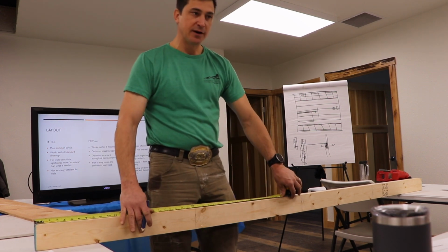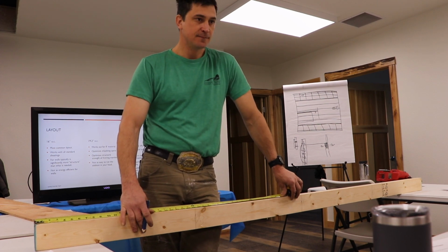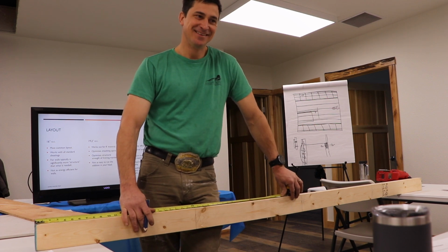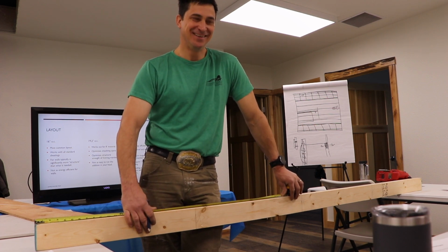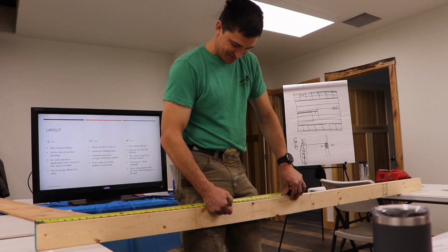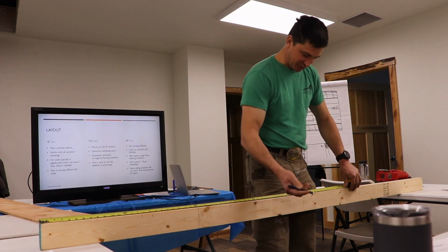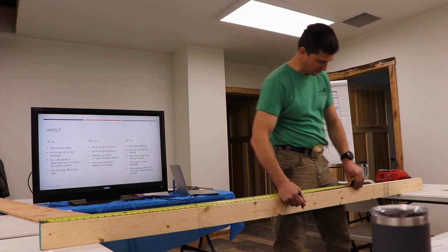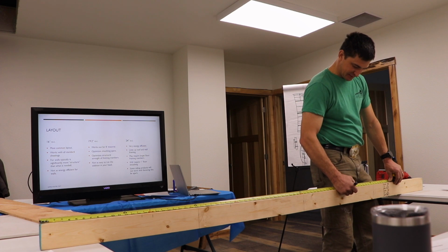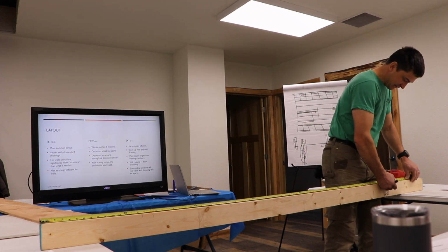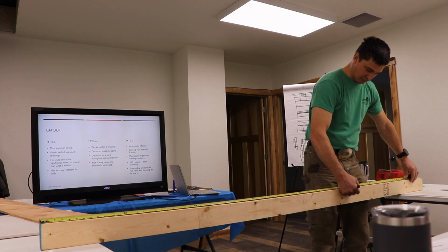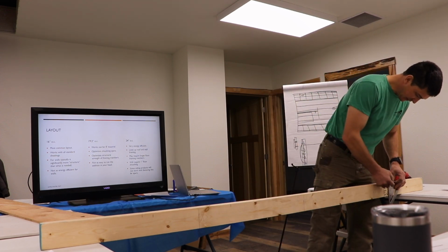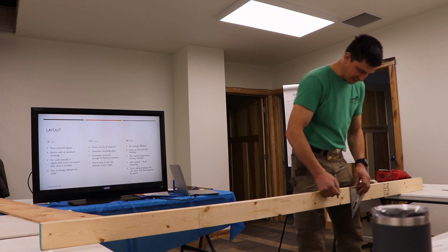Well, then where would I put my next one? The same 16 inches over, but then you go back to. Okay, so what would it be, Justin? Let's see, 30 1/4. Okay, 30 1/4. And that's pretty easy. Now that I've done that math twice, I can say, okay, I'm 46 1/4. I'm 62 1/4. 78 1/4. So on. And so then I can go, where'd that line go? I put my marks on there.